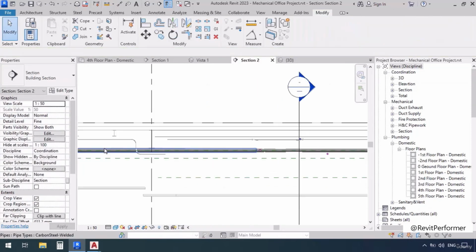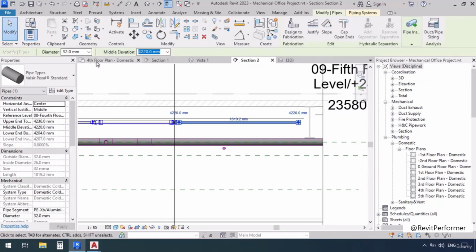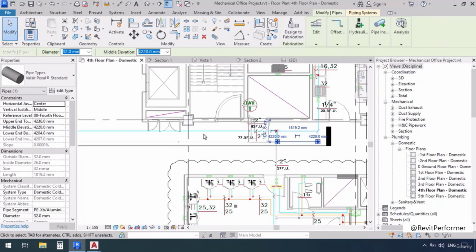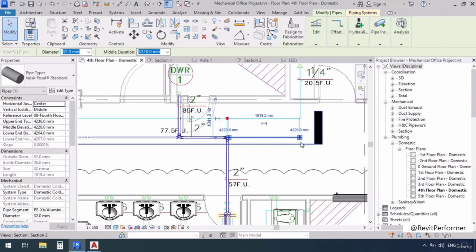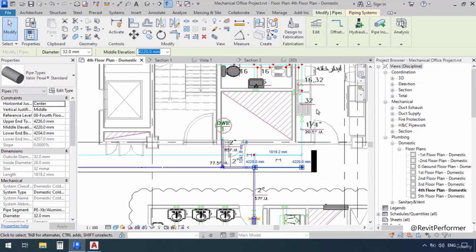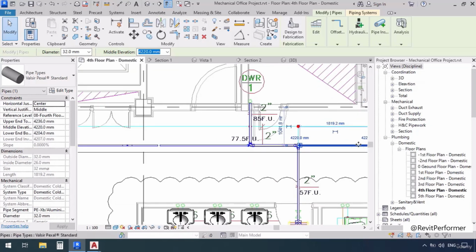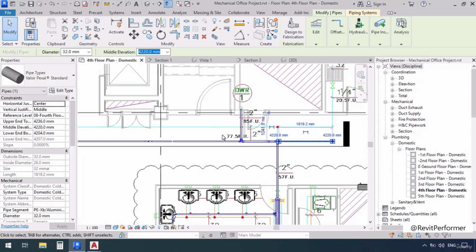Now let's go back to that other end. This one right here, I'm going to select it, then go check in the plan to see where it goes. We haven't drawn the rest of it yet, but it's going to be going up. But still, I'm going to check to see if there are any beams around here, which there aren't, so we didn't need the elevation. But in case we did, we want to change the elevation back up. We could just keep it at that low elevation, and more exactly, we could keep it at the same low elevation here at the split. So I already did that.